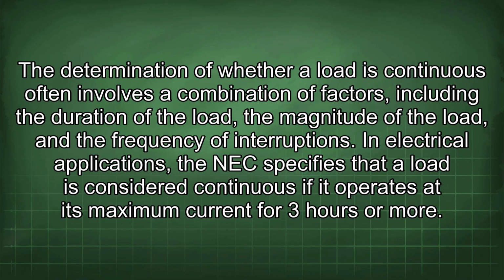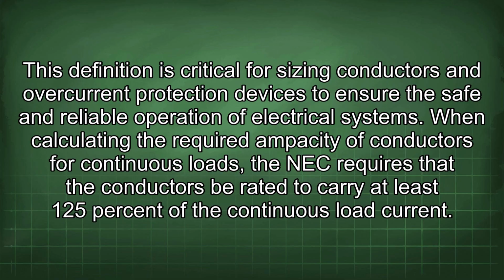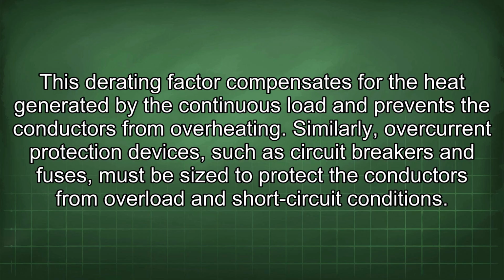In electrical applications, the NEC specifies that a load is considered continuous if it operates at its maximum current for 3 hours or more. This definition is critical for sizing conductors and overcurrent protection devices to ensure the safe and reliable operation of electrical systems. When calculating the required ampacity of conductors for continuous loads, the NEC requires that the conductors be rated to carry at least 125% of the continuous load current. This derating factor compensates for the heat generated by the continuous load and prevents the conductors from overheating.